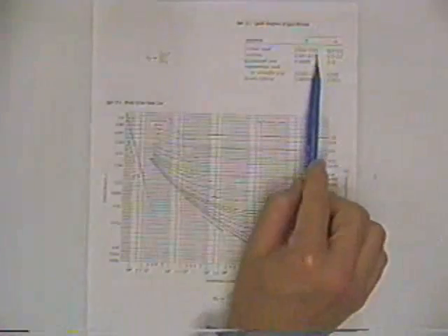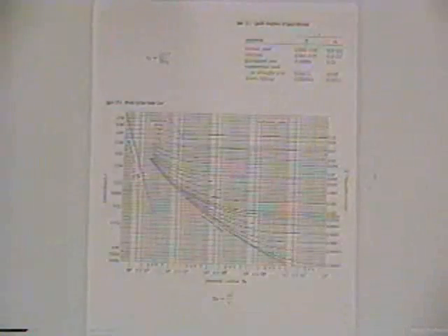And this is an absolute roughness. So if you picture a pipe, and inside the pipe, and people actually in some of the early experiments glued sand grains inside the pipe so they could have a measured amount of roughness, and then they could change the roughness. So that epsilon is a representative average roughness on the inside of the pipe.